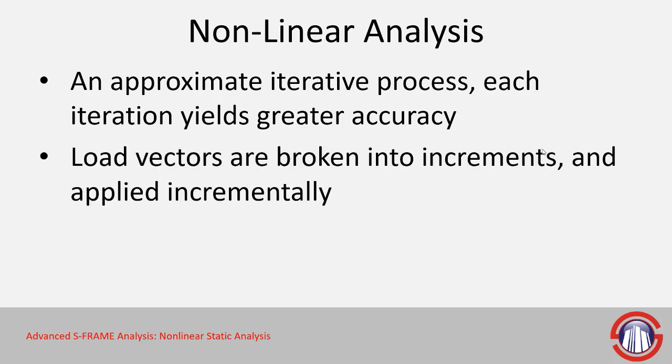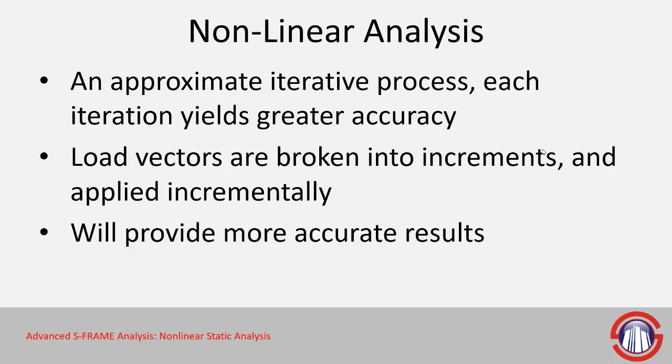Basically, the load vectors are broken into increments and they're applied incrementally. And it will provide more accurate analysis results versus its counterparts like linear and p-delta static analysis. It also allows for nonlinear elements, which we'll look at in later videos, and the option to consider not only nonlinear geometry behavior, like large displacement analysis and p-delta effects that we already talked about, but you can also define nonlinear material behavior using link elements.